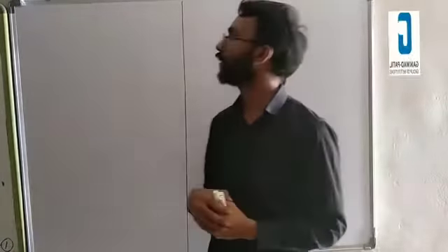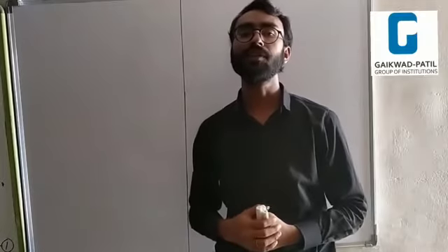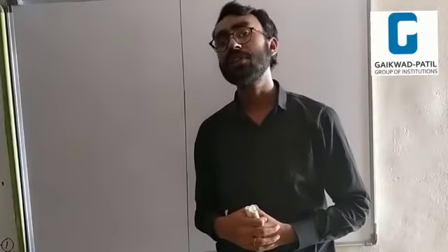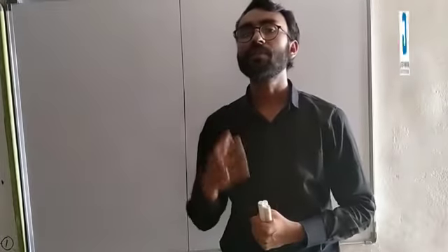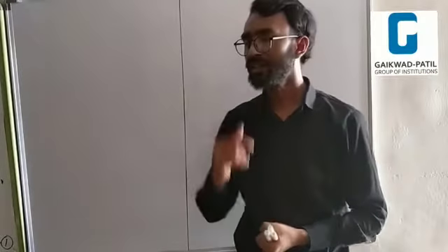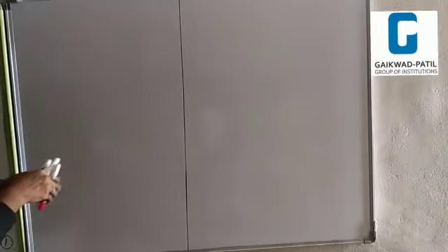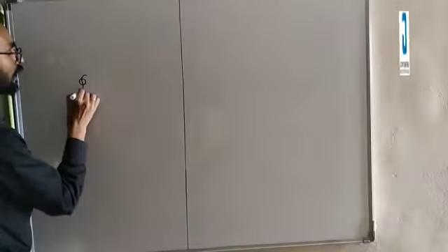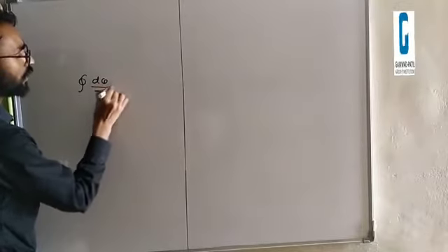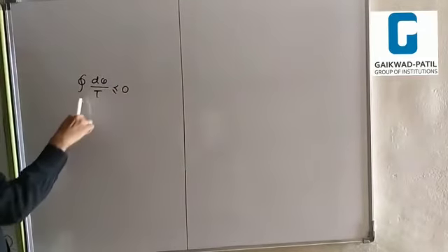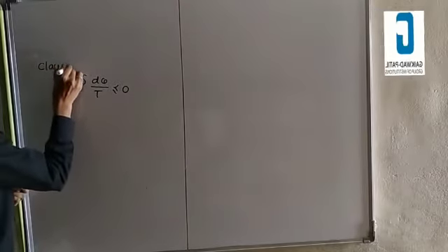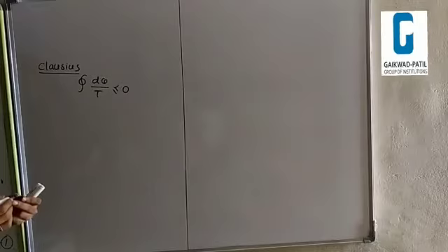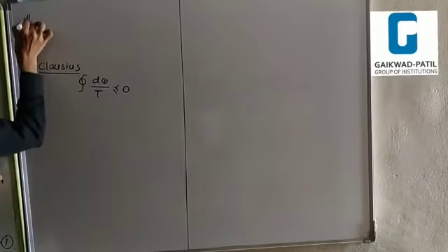And today I am going to discuss the important topic of entropy. What is entropy? Entropy is used mostly in engineering thermodynamics. In the last lecture we already discussed the basic concept of the Clausius inequality. The Clausius inequality is the cyclic integration of dQ over T is less than or equal to 0. This is given by Clausius. Now I will discuss entropy.